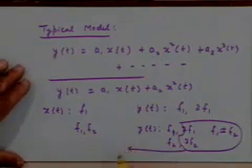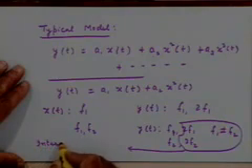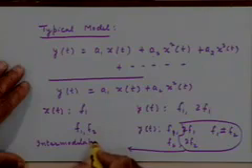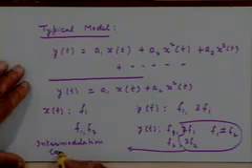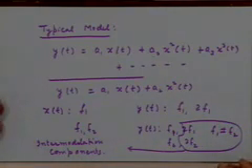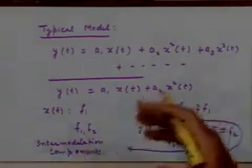And we call these components intermodulation components. And this nonlinear distortion is for this reason also called harmonic distortion or intermodulation distortion, because different frequency components modulate each other to produce additional frequency components, right?